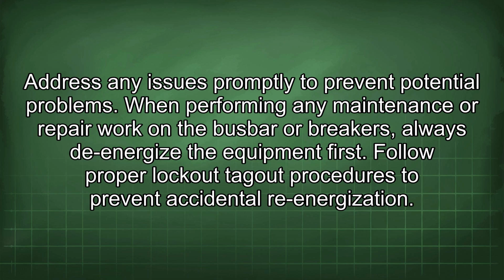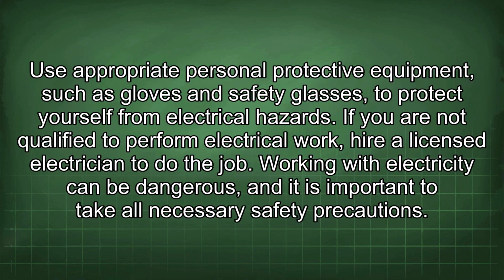When performing any maintenance or repair work on the busbar or breakers, always de-energize the equipment first. Follow proper lockout-tagout procedures to prevent accidental re-energization. Use appropriate personal protective equipment, such as gloves and safety glasses, to protect yourself from electrical hazards. If you are not qualified to perform electrical work, hire a licensed electrician to do the job. Working with electricity can be dangerous, and it is important to take all necessary safety precautions.